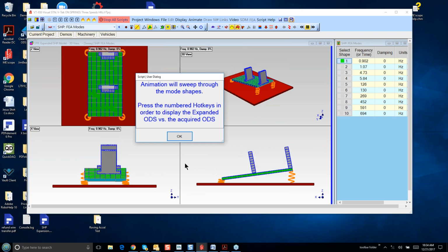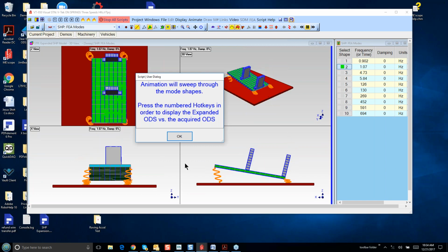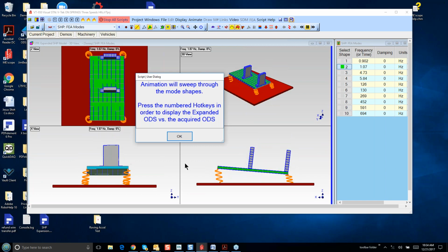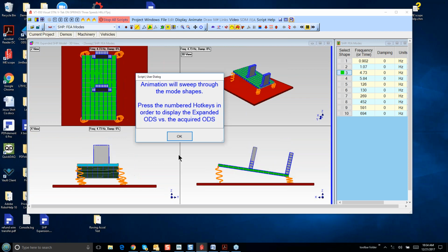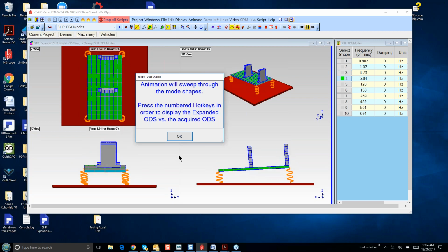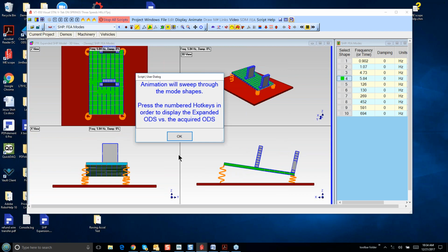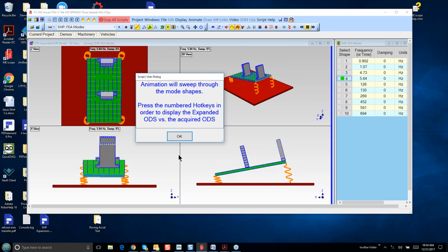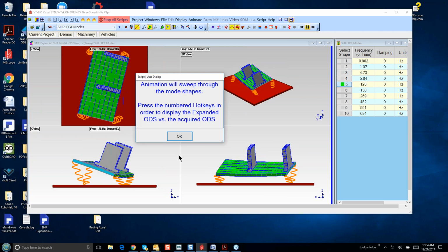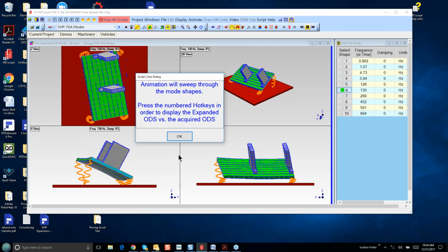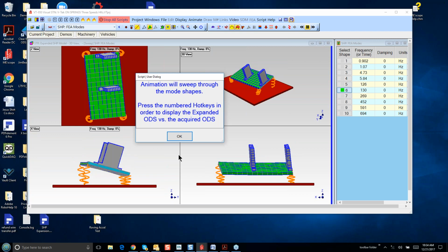So again, we started out with mode shapes that included the free motion of the structure. And those are the easiest mode shapes to get from an FEA solver. They're not typically as easy to get experimentally, although we can usually pick up a couple of the free modes depending on how the experiment is set up.